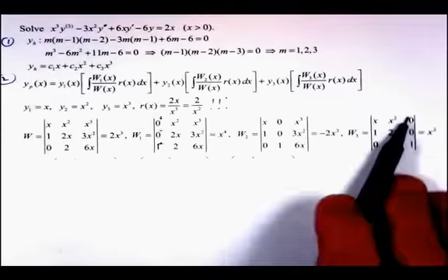We don't want that either. We don't want this distance down too big, and we don't want any big slopes in here as well. So mathematically, y, which is the distance down, and its derivative, which is the slope of the deflection curve at any point, aren't too big at any particular point.